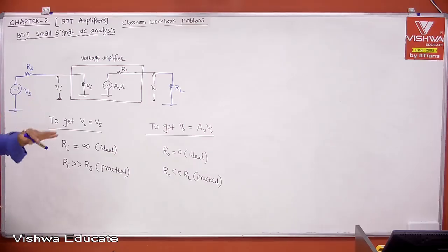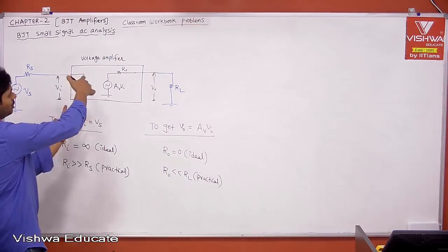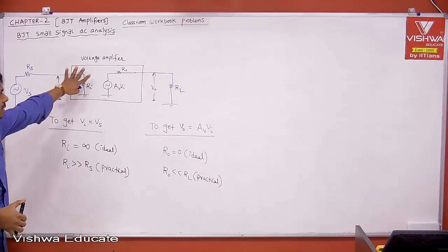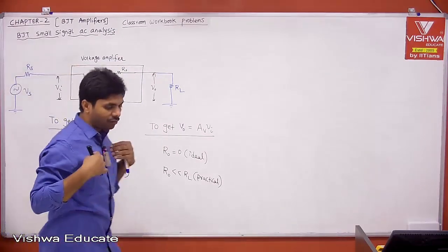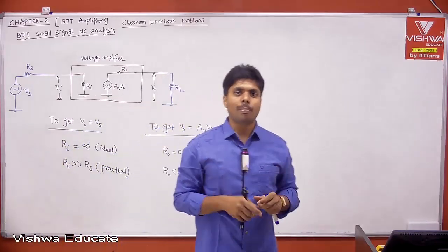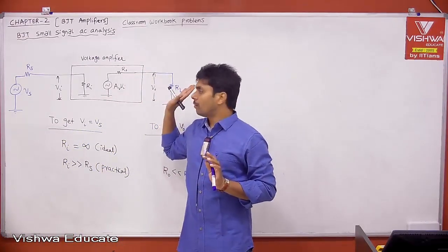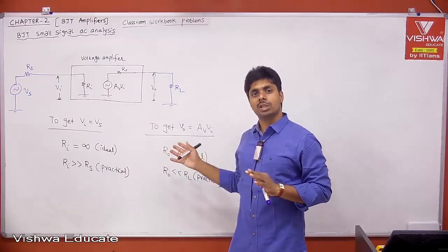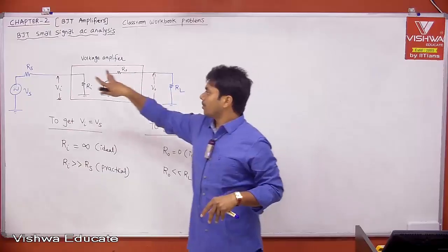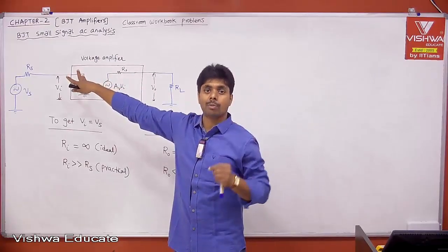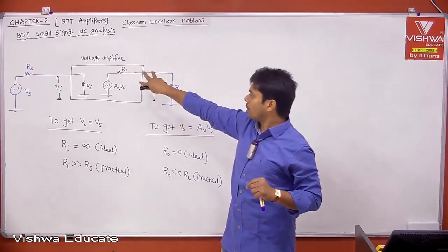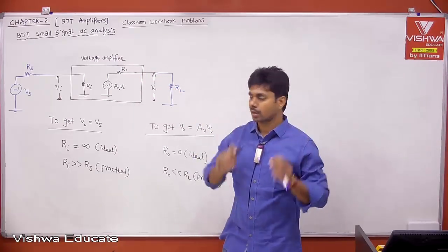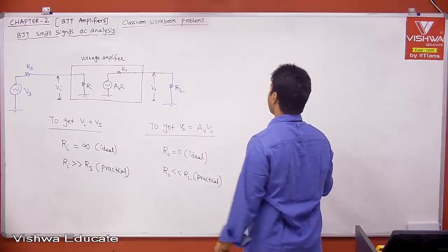But now I'm trying to use this as a reference to explain something else, which is for the current amplifier. Now this is for the voltage amplifier. Typically by default I want it for a voltage amplifier only. Example, op amp. Op amp is a voltage amplifier. Therefore input impedance should be infinity, output impedance should be 0. To achieve those, I told you, a CC amplifier at the input stage which will give you 1.7 mega ohm or 1.8 mega ohm, and a CC amplifier at the output stage which will give you 40 ohm, 50 ohm, which is your output impedance. Okay, done.